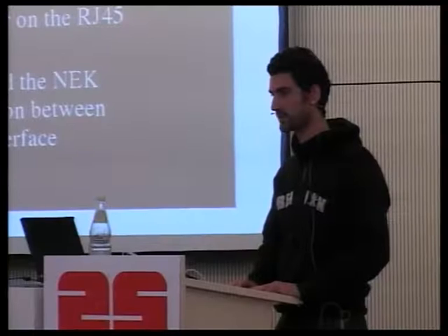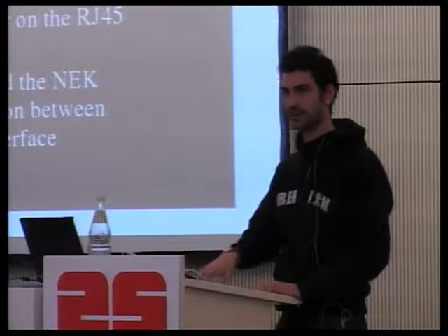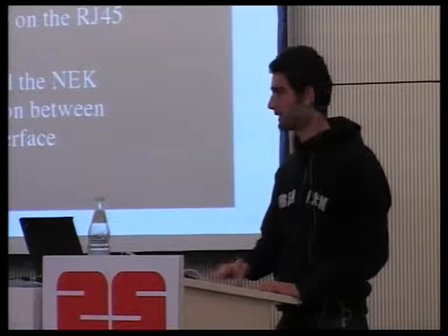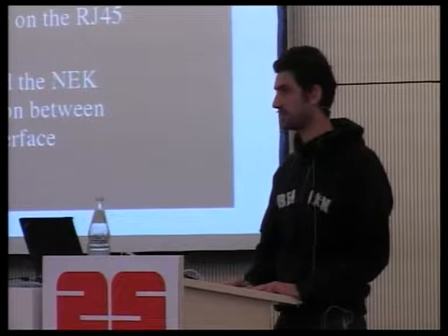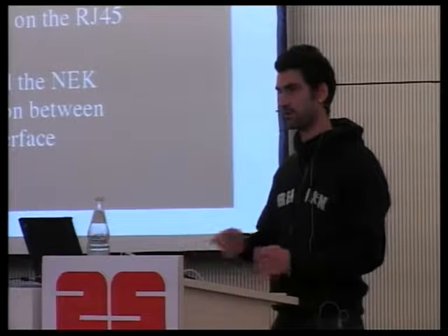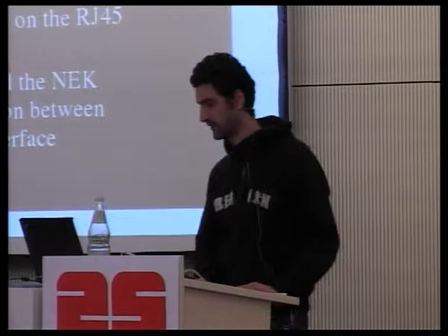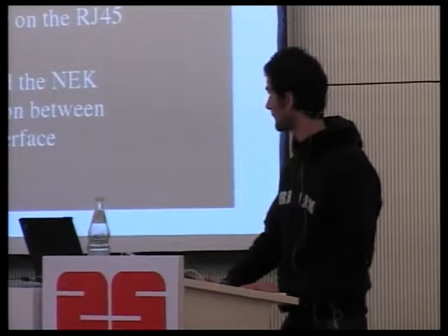The next generation, HomePlug AV, which we are looking at, uses AES 128 encryption, and the network architecture is basically in two parts: coordinator and stations. It's not really a master-slave architecture, but similar to that, where the coordinator is managing the whole network and will give access and credentials to every station connecting to the network.